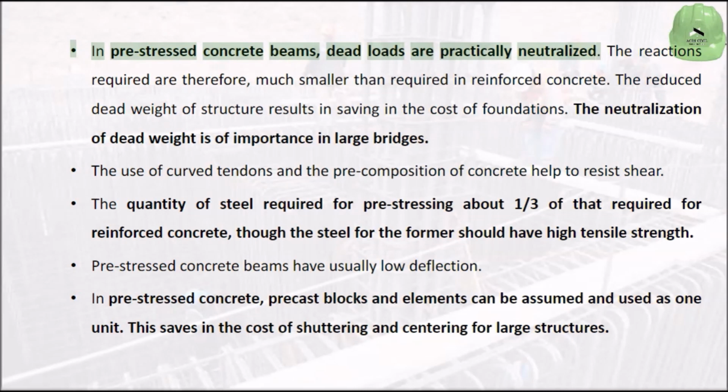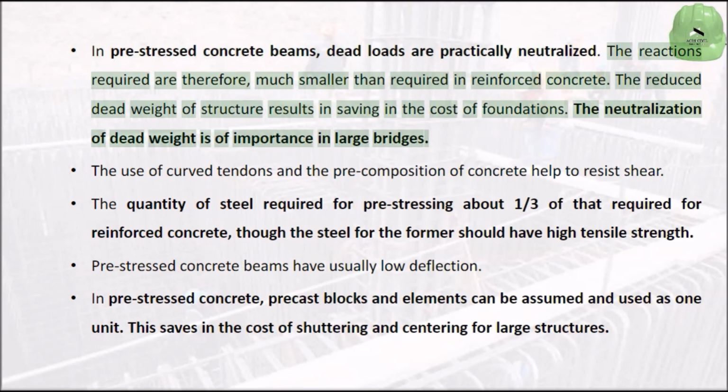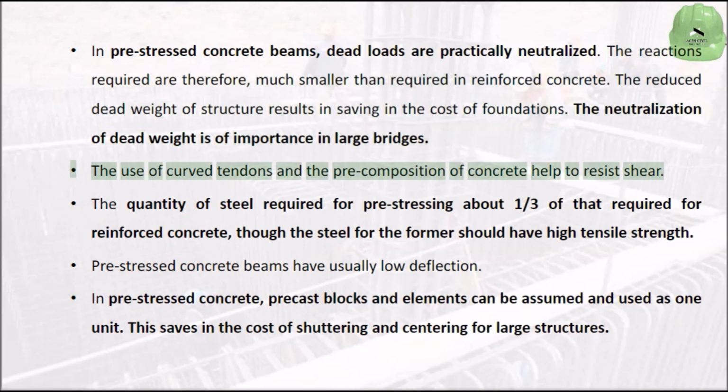In pre-stressed concrete beams, dead loads are practically neutralized. The reactions required are therefore much smaller than required in reinforced concrete. The reduced dead weight of the structure results in savings in the cost of foundations. The neutralization of dead weight is of importance in large bridges. The use of curved tendons and the pre-compression of concrete help to resist shear.